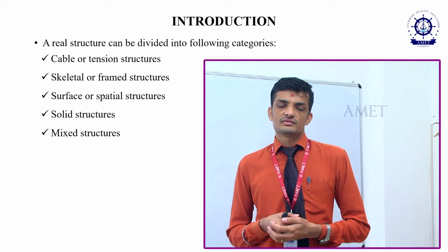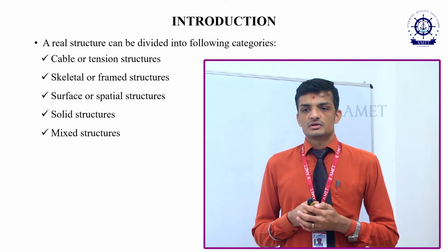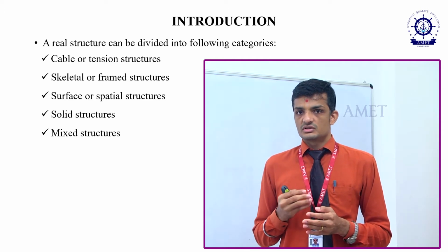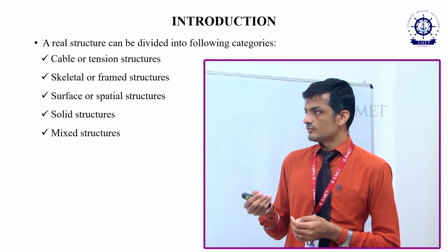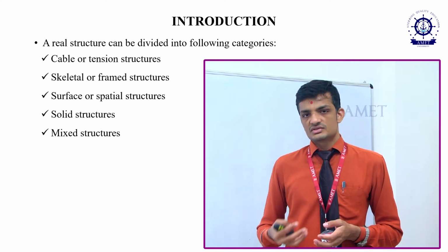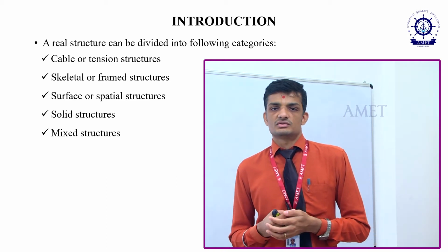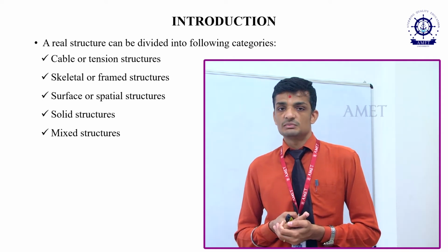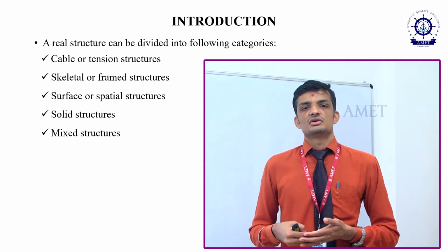This is something interesting. For example, if you have to classify the problem to understand how you are going to solve it, because unless you have an idea of the behavior of the structure, classifying becomes a tough task. So here I have mentioned 5 classifications. Any structure could be classified as the cable or the tension structures. We are always exposed to the tension. In offshore engineering, we have something called tethers. They are the members attached to the offshore platform, mainly TLP, keeping it at a particular station so that it will not move, and they are exposed to various forces.